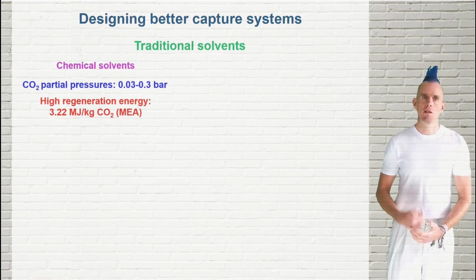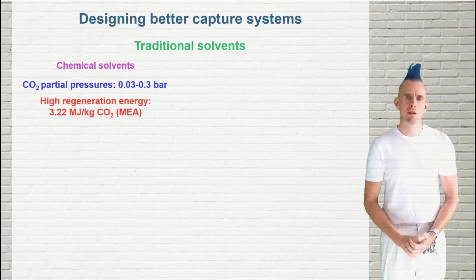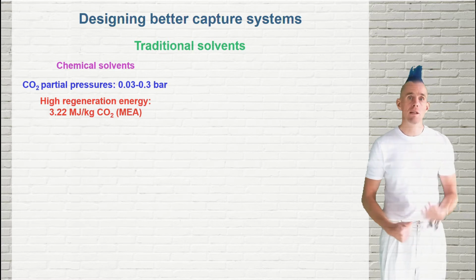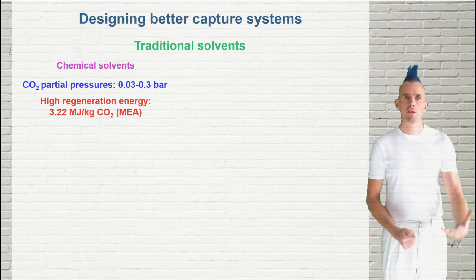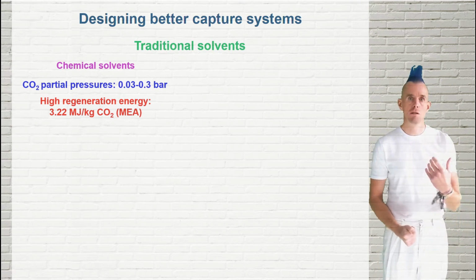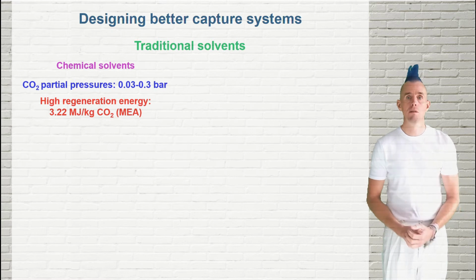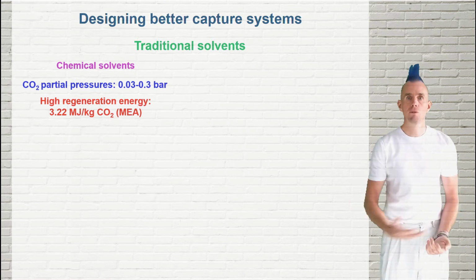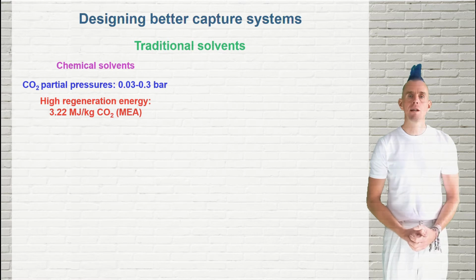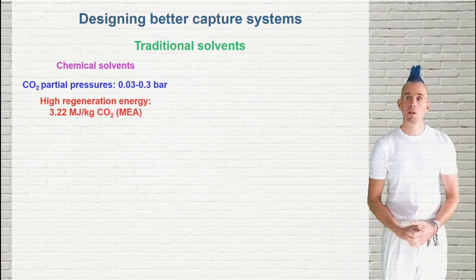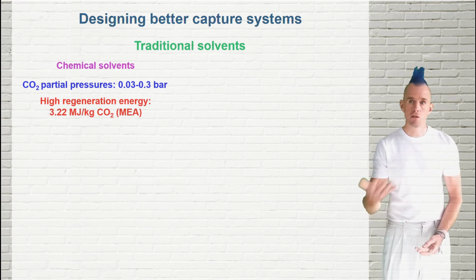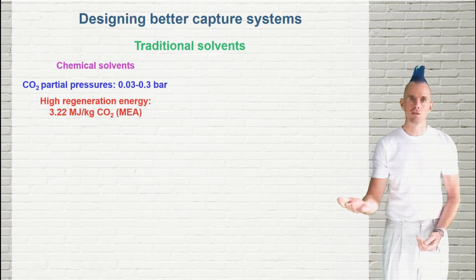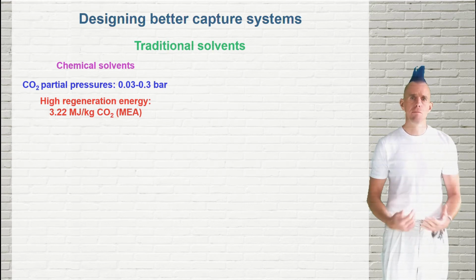Now, chemical engineers have been doing carbon capture for a very, very long time. They didn't call it carbon capture, they called it acid gas capture. Because if you look at ammonia production, for example, carbon dioxide has to be captured in ammonia production because carbon oxides start to poison ammonia catalysts. Hydrogen sulfide is routinely removed out of refinery gas streams. It's called sour gas because hydrogen sulfide is a product of hydrodesulfurization of fuels. Hydrogen sulfide is another example of an acid gas. Acid gas removal is something that chemical engineers are very, very good at and have practiced for a very, very long time.